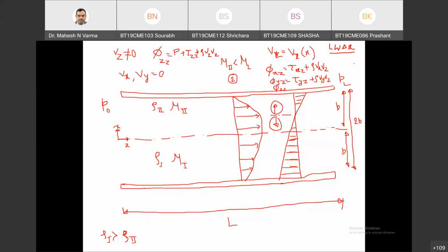So what is the gravitational force acting in the direction of flow? Sir, along the direction of flow, gravity will be zero. Very good. It is given that the flow is horizontal in a thin slit, and this will be my G, so in the direction of flow Gz equals 0. We need not take it because I am taking the Z momentum balance equation. There is no gravitational force acting in the direction of flow.